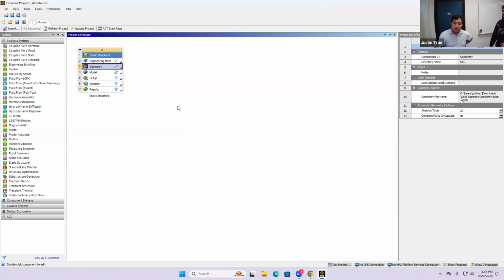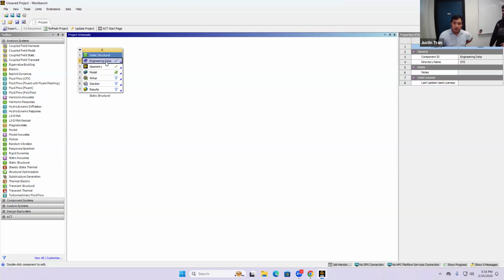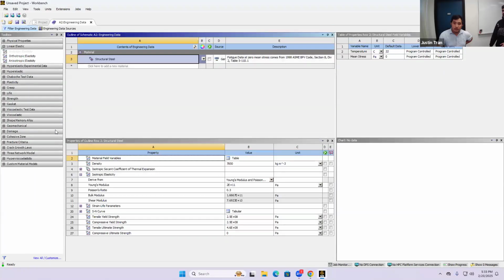Okay. So before we actually open this up in ANSYS Mechanical, let's load in a custom material property. If you remember from activity 2, we did this for the first time. In activity 2, we created a new custom material for aluminum. So we're going to load aluminum in as well here, but we're going to do it in a slightly different way. If you recall from last time, to add a new material property, you need to double click on engineering data. Double clicking on engineering data, you can see here that we have this one material, which is structural steel. So let's add a second one.